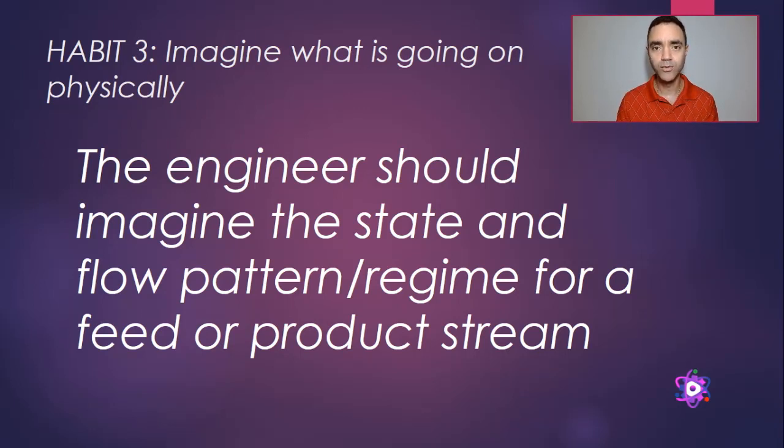For instance, you are dealing with a saturated stream, and based on the environmental conditions, eventually you will have condensate formation in your pipeline. Because of that, you will need to add a separator vessel. Or if you are doing pipe sizing and you increase the velocity too much, you must think about the vibration that can happen in the field, for instance.